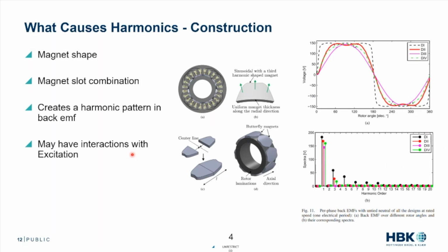The motor construction, and this is almost more specific to permanent magnet motors, is very important for the harmonic profile. So I've got a lot of pictures here, so I'm going to talk through it. Basically, we're going to start with picture D and work backwards. We have a rotor with a magnet on it. These little gray guys are our magnets. We see the magnets over here.